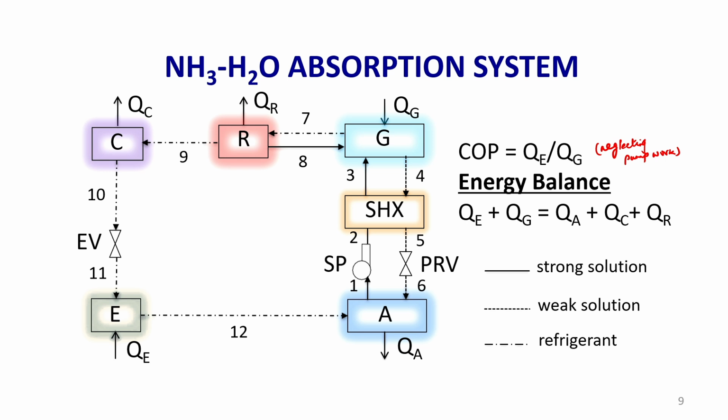It is because the evaporator is at low pressure. Now, this portion is similar to the vapor compression cycle. In the condenser, a phase change process occurs, vapor is converted into liquid, then the heat is removed. Here the refrigerant is pure ammonia, here it is pure ammonia, here also it is pure ammonia. The concentration here is 0.99, here also 0.99.